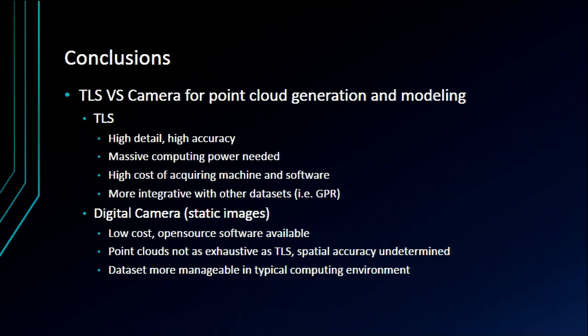and we're cleaning up the 3D version of what we did, and we're beginning to compare it to the total station, to the LiDAR, because the LiDAR, it's light ranging, and it's perfect when it hits there. So we're cleaning up the points to see how well it can then create a real inexpensive 3D model, and secondly, how accurate that 3D model is. Because as you can expect right now, our accuracy is with the LiDAR, and we're trying to start matching that.